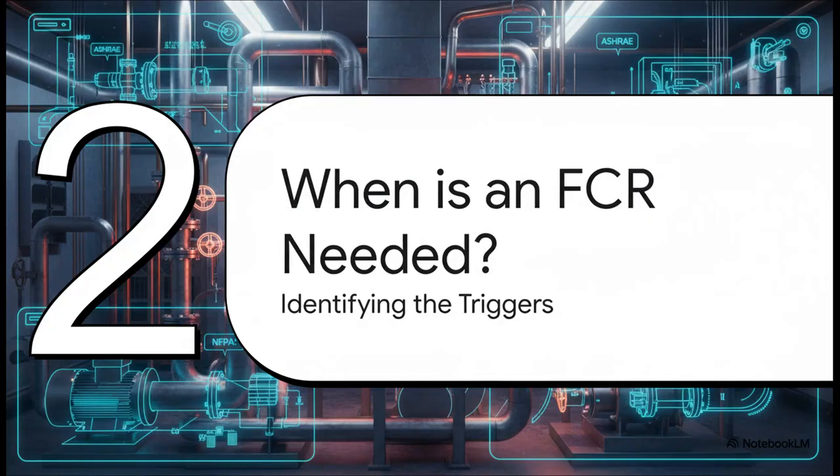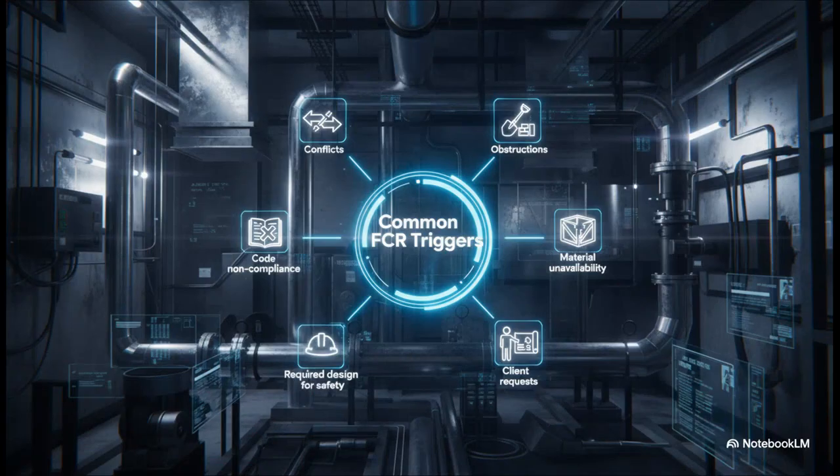Okay, so we know what it is. Now let's get into when you need to kick one off. Your interviewer is going to want to see that you can spot the common situations that scream, we need an FCR. These are the usual suspects, right? You might find a clash between trades, like HVAC ducts and plumbing pipes wanting the same exact spot. Or you might dig and hit an old foundation that wasn't on any record.